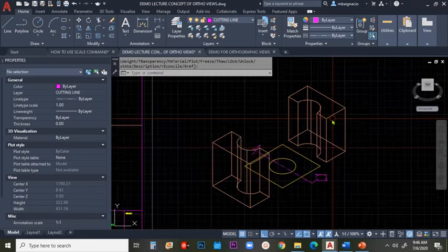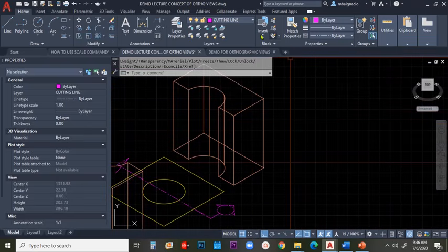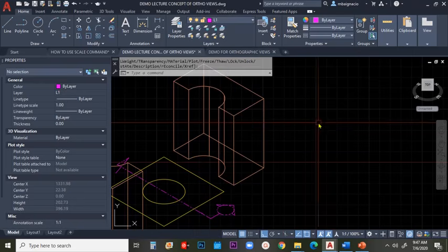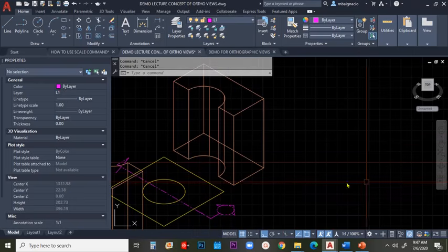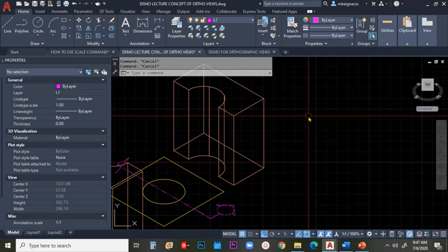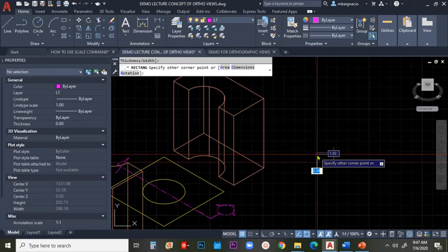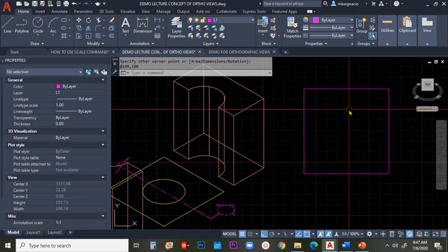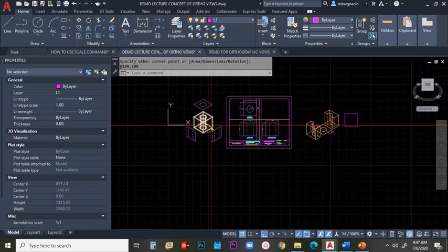But first we need to convert this very same figure to two-dimensional view. So I'll just turn on my layer 1. I need the area in terms of the length and the height of the object. So rectangle again. I'll create at 100 comma 100, which is the area of our rectangle with reference to this face and this face also.